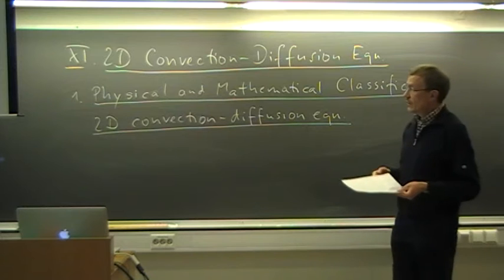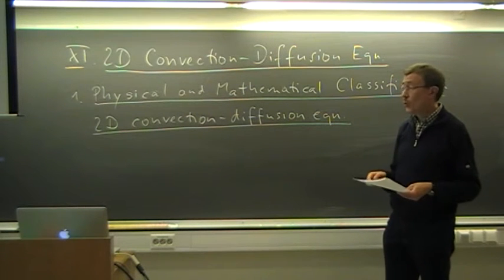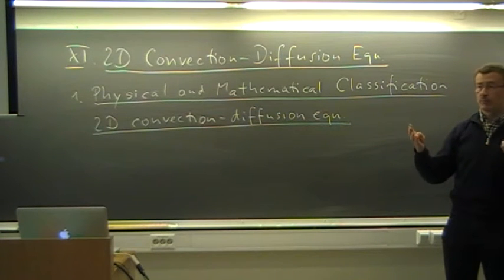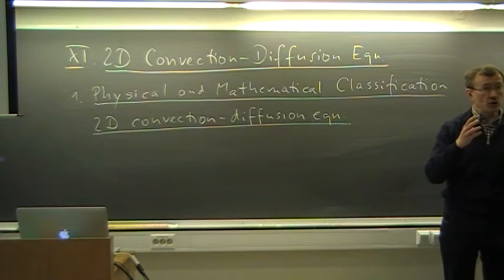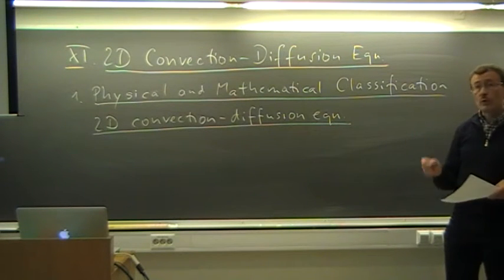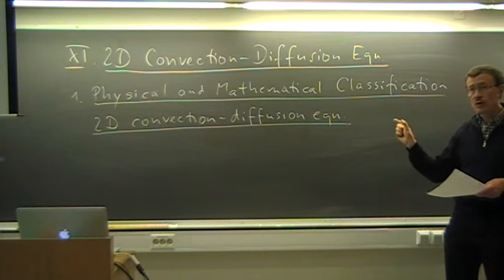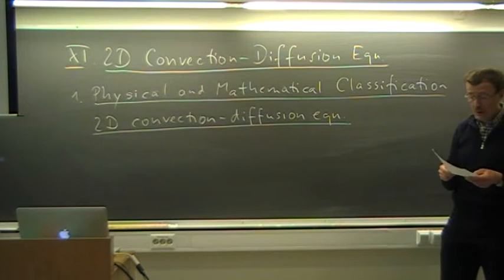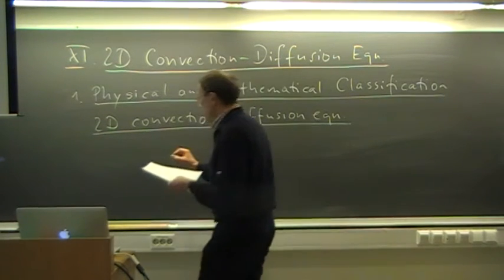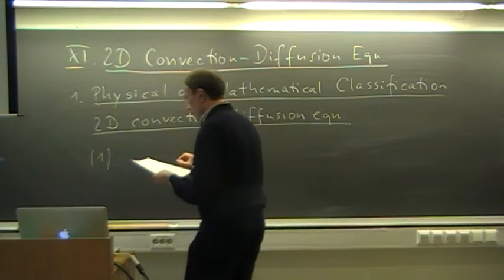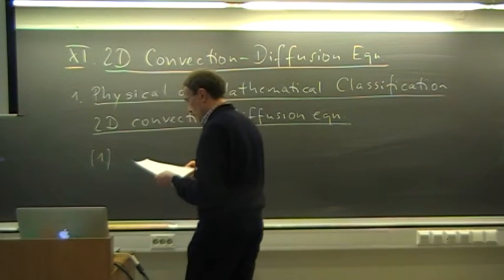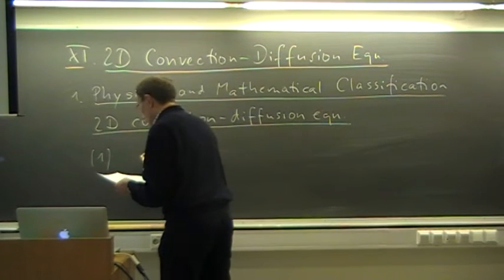And then we looked at the 1D linear advection equation, where we only had advection present, and there is only a velocity profile or whatever profile of temperature or concentration is just transported without change. And in this equation we have both present, both diffusion and advection. But advection is here called convection, that is a convention. And the equation looks like this. We have a physical property u. We take example later on, which might be temperature, concentration, or even velocity itself.